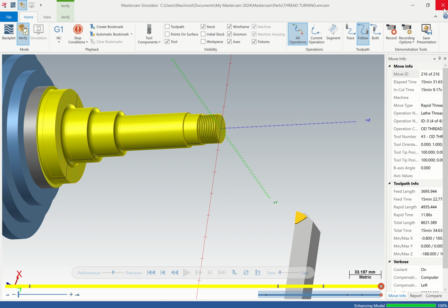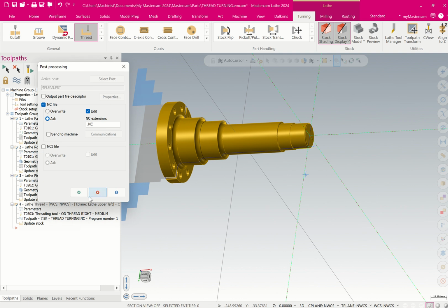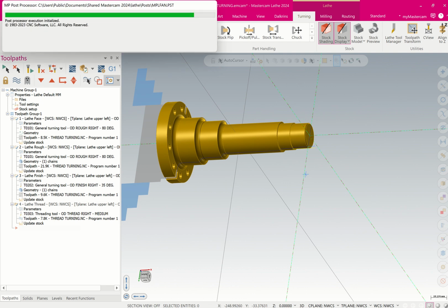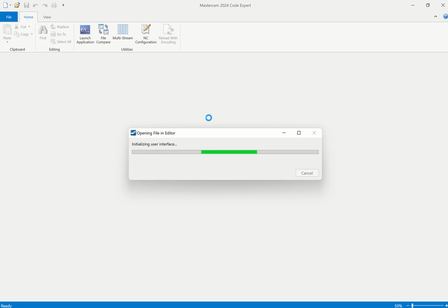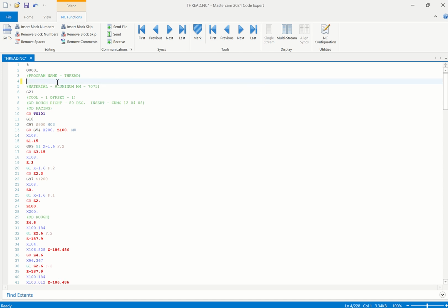It's okay. You can generate a G code, select all of them, click G1, then okay. Thread. Just calculate, then generate the G code. I'll show you the G code. Now how to also edit the G code in the program. You can edit the G code. So I want to remove even this.